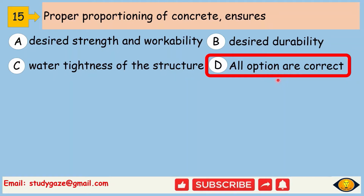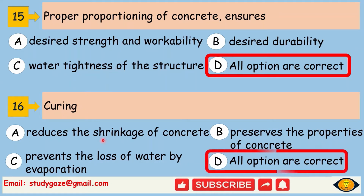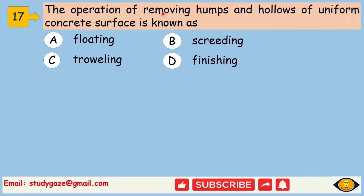Next, curing. Curing reduces the shrinkage of the concrete also, preserves the properties of concrete also, and prevents the loss of water by evaporation. So the correct option is D, all options are correct. Next, the operation of removing humps and hollows of uniform concrete surface is known as. So this process is called screeding.